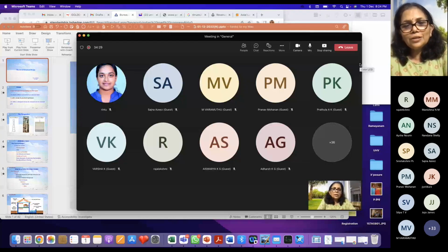What exactly do you find out? First, you find out the reactions, isn't it? Yes or no? Yes. So after finding out the reactions, you then go on to find out the bending moment at various sections, and you draw the bending moment diagram and the shear force diagram. This you studied in the third semester.